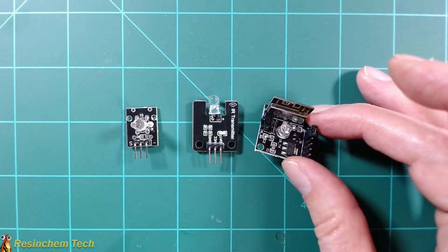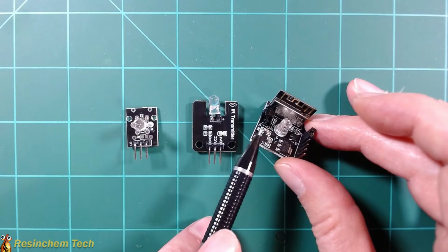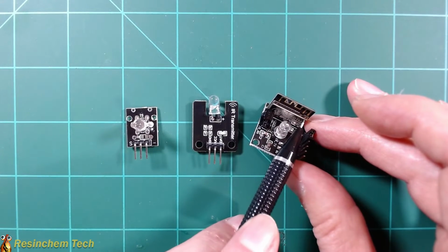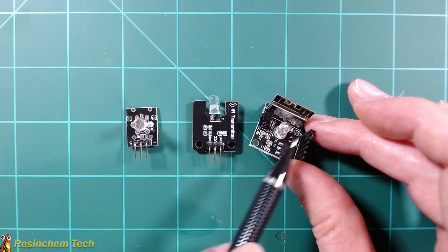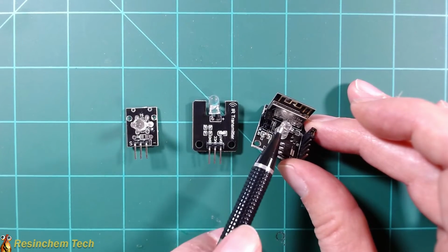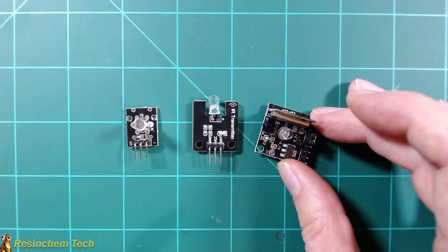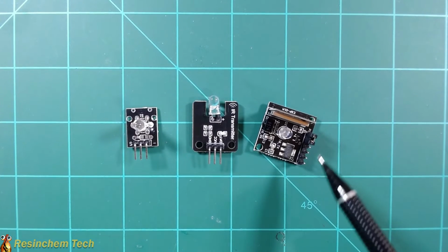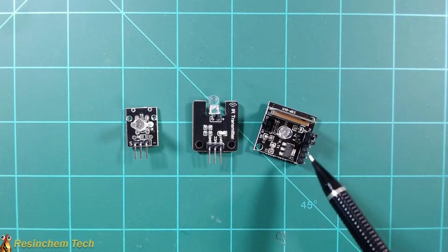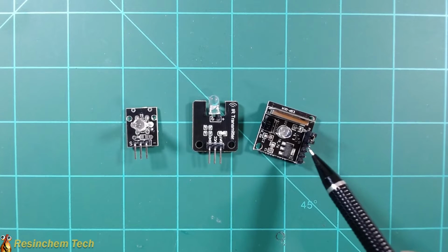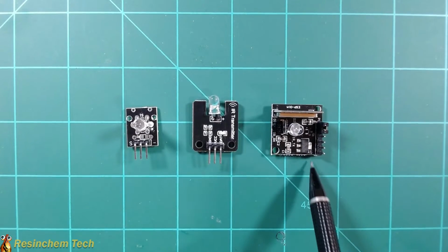This third option I didn't try, but it is an interesting idea. It's got both the IR transmitter and receiver on board with an ESP8265, which will work with ESPHome. But this is kind of an all-in-one option that you wouldn't need a separate ESP8266 or ESP32. It is a little bit trickier to use because you do have to flash your ESPHome code using a USB to TTL adapter and the RX and TX pins here on the board. So I did not test that one, but it is an interesting option that might work just fine for you.